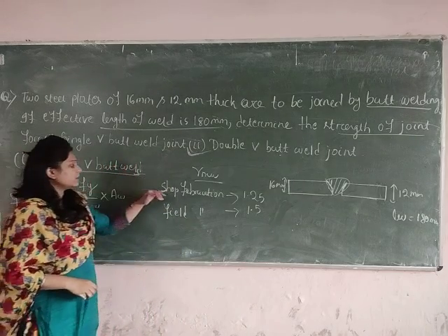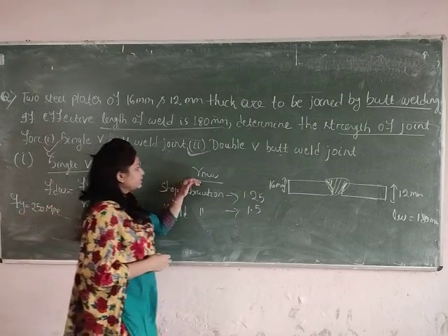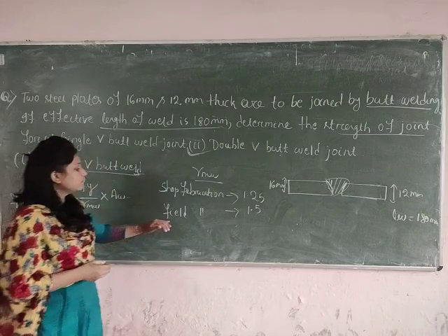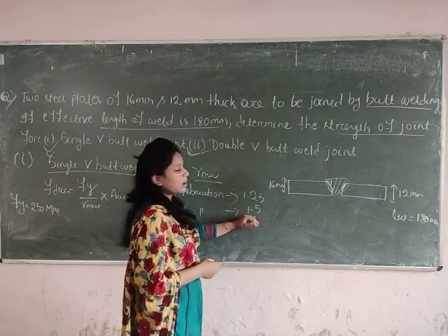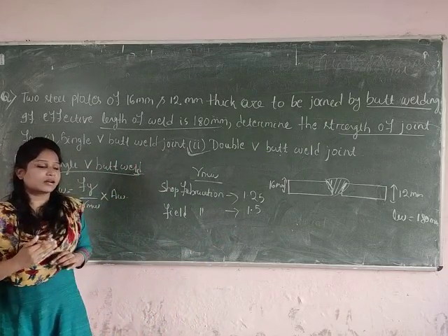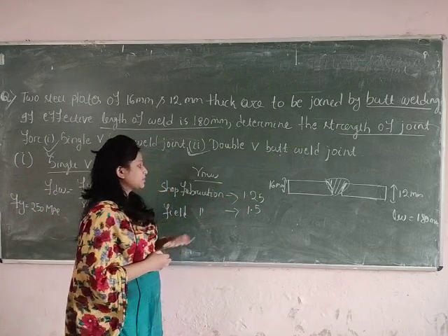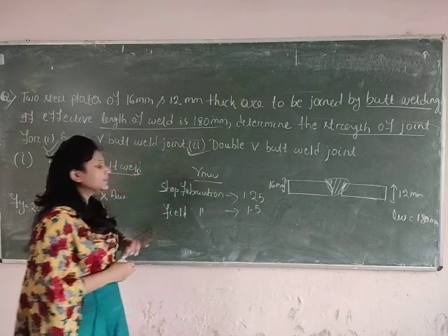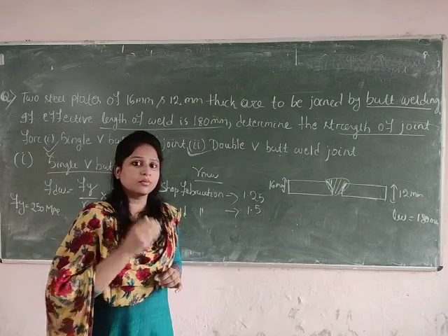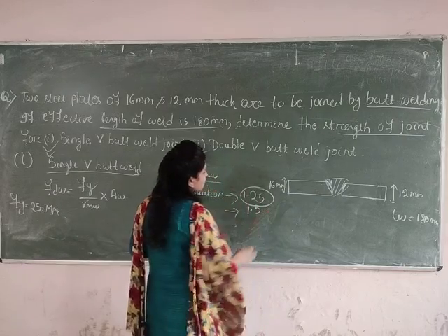So if the welded connection is done in workshop, then you take the value of gamma mw as 1.25, and if the welded connection is done in field, then take the value of gamma mw as 1.5. As in workshop, the connection is done very properly, so the partial factor of safety value is less than that of the field condition. As in case of field, the work can't be done as properly. That's why for shop fabrication the factor of safety value is less.